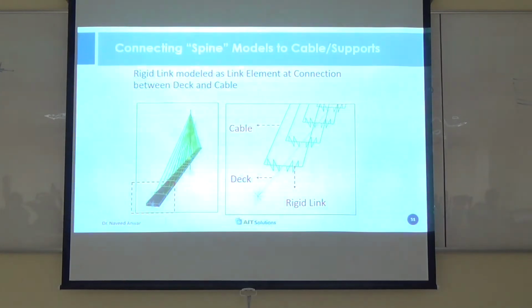Once you're done, then for the final design, you move to a more sophisticated model. Otherwise, it will waste a lot of time. So the first model can always be a beam model, a simple frame model, a 2D model, and then you get the overall response, get the section dimensions, then you go to the next level and make a refined model.